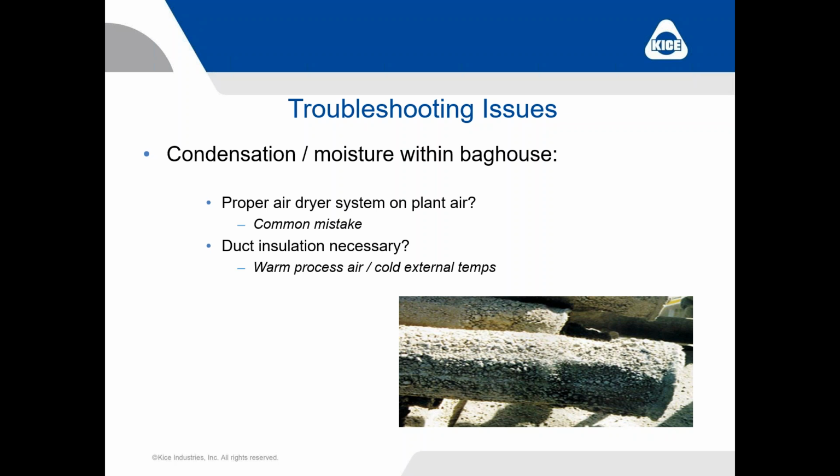With our high pressure cleaning system, our Venturi jet style filter, where we use plant air, it is not uncommon for us to get phone calls wondering why filter bags turn out looking like they show here on this slide. You must have a good air dryer system on your plant air and a good airline filter prior to the baghouse to make sure you're using clean, dry air to clean those socks. If you're not, all you're going to do is shoot condensation and moisture down inside of these filter bags, and in short order, you're going to have a gummed up, plugged up filter that's not going to do anybody much of any good. So again, sometimes the easiest, simplest things are the right answer. Make sure you have a good air dryer on your airline.